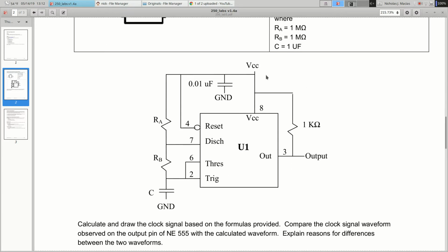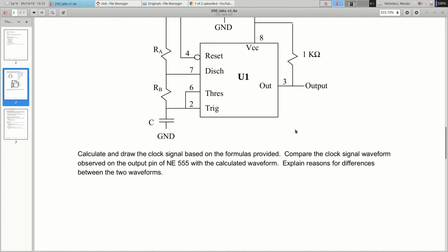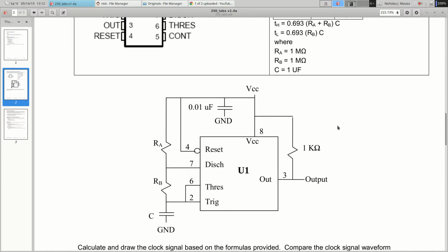Alright, clear on how to wire that? So we're omitting the 1K? Yeah, leave this 1K off. Alright. Keep going back up. So it looks like your connect, so right where the 0.01 uF is, looks like that's being connected to ground and voltage.